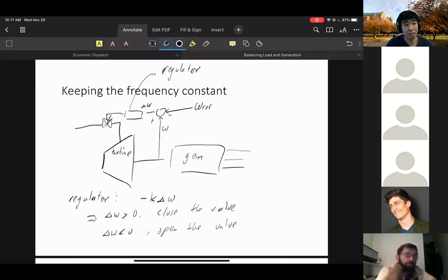This is its own special area of how you design a regulator control for a generator, because a generator is normally some nonlinear system. So it's not so simple. You don't just slap a negative feedback on the generator and it always works, right? So normally this is a high order controller. You design this still mostly in the frequency domain. For the people who take control systems, remember the Laplace transform, and we are going to design this.